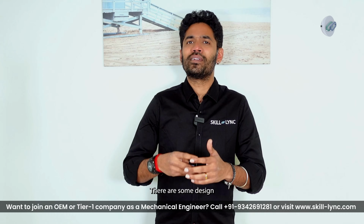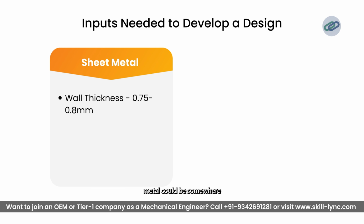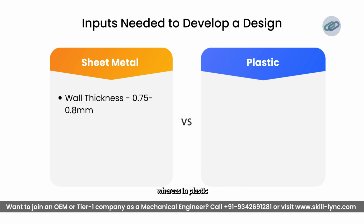Right? There are some design constraints for sheet metal versus plastic. The minimum wall thickness in a sheet metal could be somewhere approximately 0.75 to 0.8 millimeter plus. Whereas in plastic, it varies with respect to the processes.